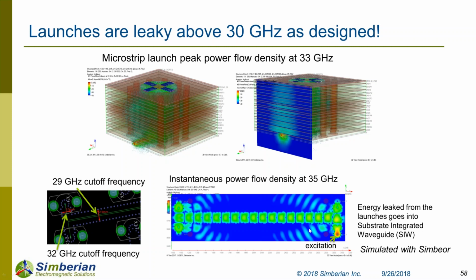And actually, in the full report we have one of the structures, a single-ended via where the return via was far away. That one lost localization already at around 4 gigahertz or so. Vias are really nasty things at high frequencies, especially through-hole vias, which can inject noise into every cavity. We have seen on this board that this noise spreads really far away. It doesn't get damped. You said 4 gigahertz, Marco?